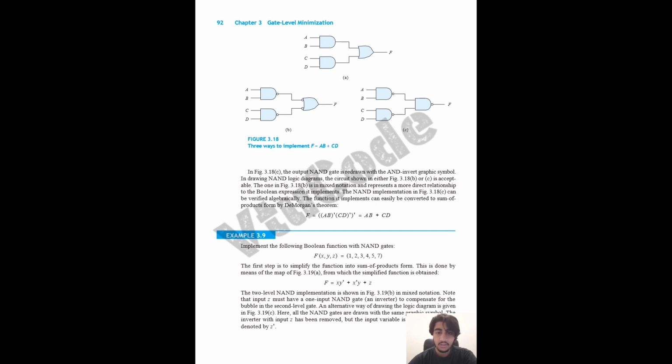That is one part. Next, we have already taken x, continue the same line downward, take the NOT gate, that gives you x bar. Similarly, we have the y bar notation, take that as a y before putting the NOT gate, go for multiplication, that is AND gate, and finally we have z, introduce a new z input line. So we have two AND gates here and one single z input line. Connect all these three to the OR gate to get the output line. So this is how we write the logic circuit diagram for a given simplified K-map expression.